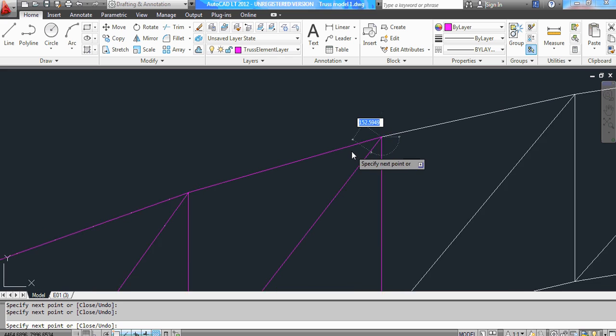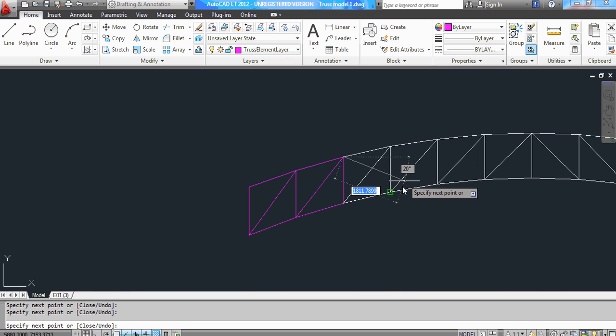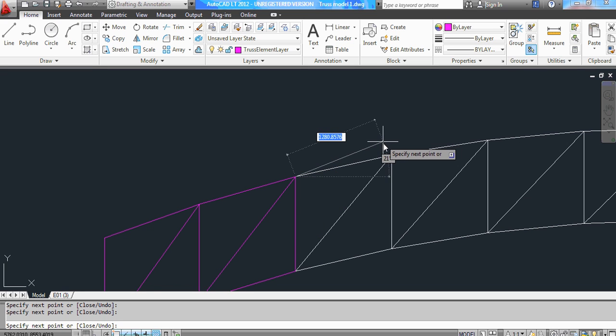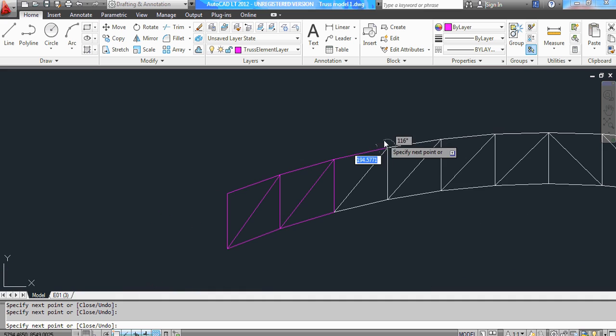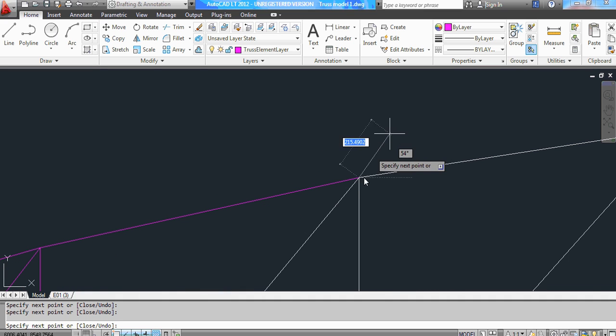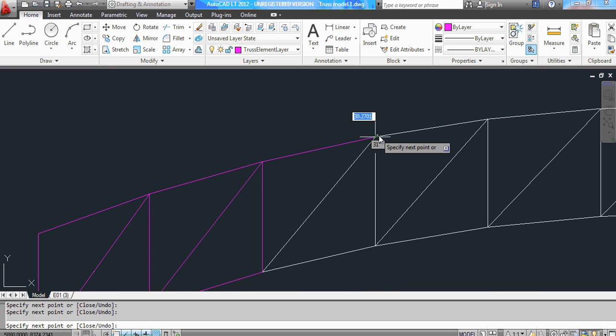And as I said earlier, don't assume that the lines are fine, for example this truss that we have, where you can see the lines are already formed. It's always good not to assume that everything is okay, and then read it off, turn it into a DXF and redirect. Because the trouble is, the person that did the trusses earlier might have drawn double lines on top of each other, and you can never know. That is why it is good to create your own separate layer, call it whatever name you want, and trace the lines by yourself. Make sure every point connects to each other.